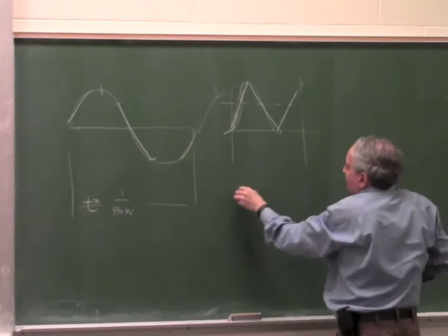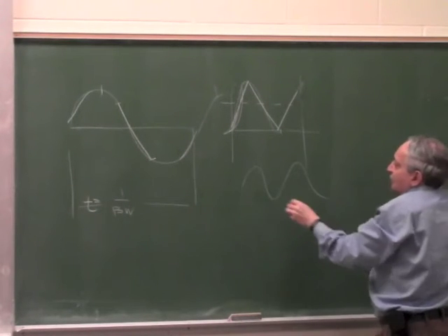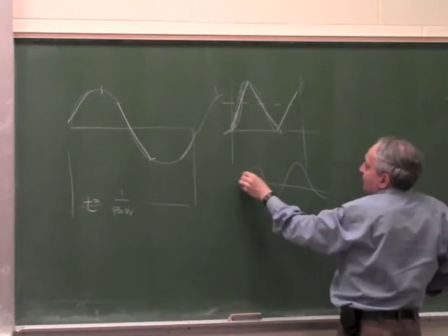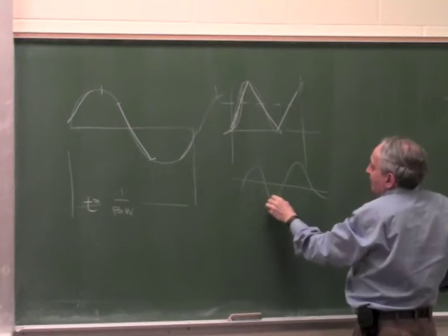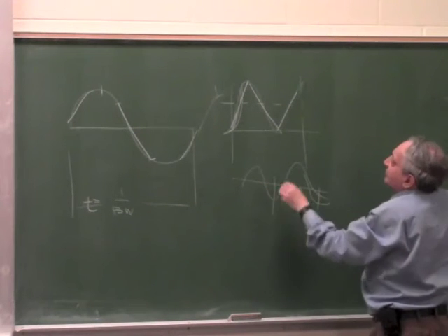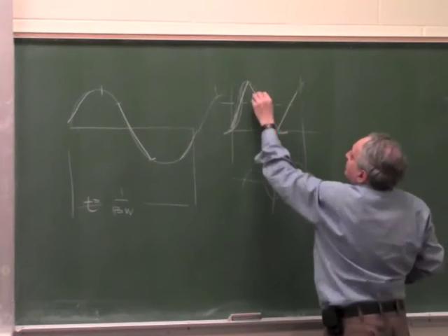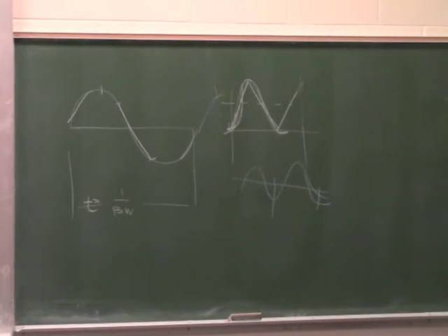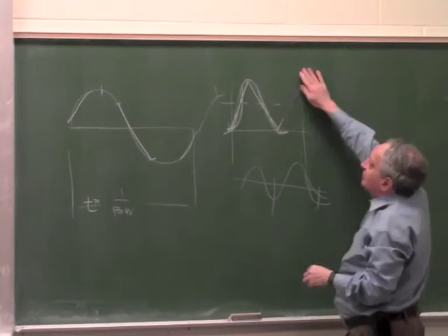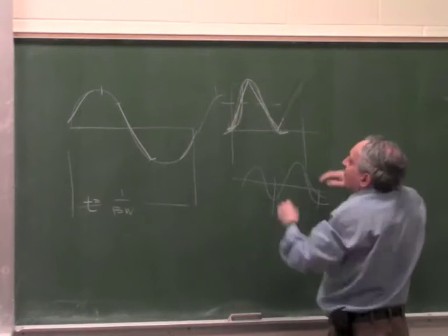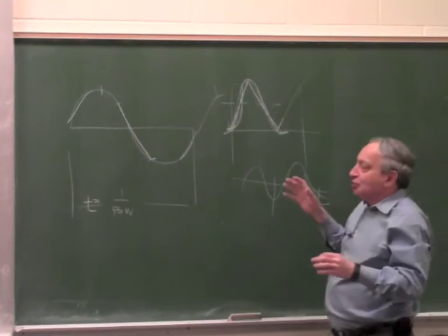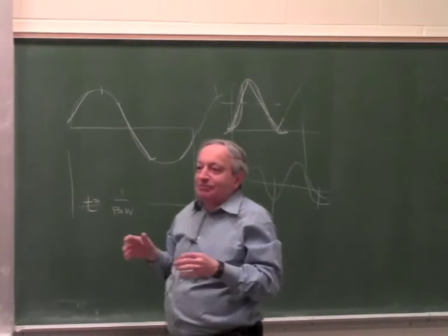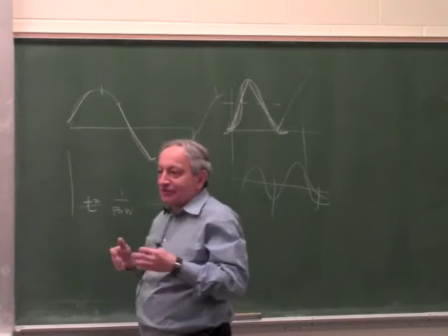that's not accurate, because if I take the sine wave and shift it above 0, so let's say I can go from here to here. I can only go up to here. This is a sine wave above 0. Okay. So you can see it contains at least twice the rise time, and actually more. So that's just to show you that the rise time is much faster than 1 over bandwidth.